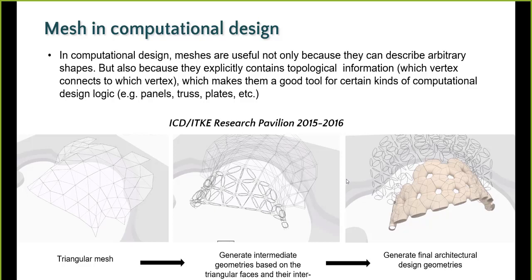So in landscape architecture, where they have really large surfaces, sites that might be miles long, or huge regions, a mesh is really the only way to store that information, because it has to be light enough that all of it can be put in, and a surface would just bog the computer down. So keep that in mind. If you have very complex models, or if you need to represent a lot of form, the best way to do it is to use a mesh.